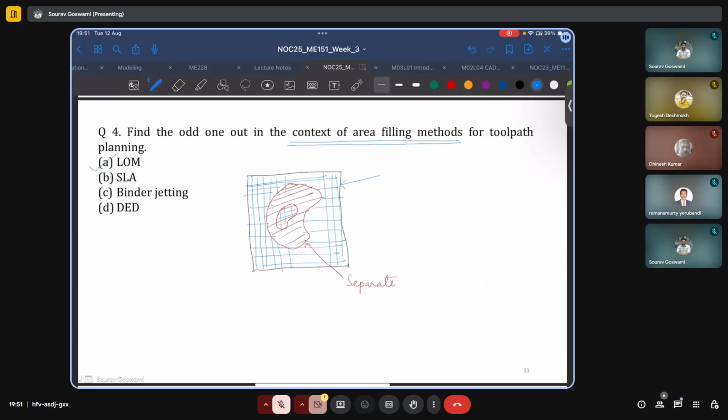But essentially, we have to separate this from the existing sheet. And that is why we are more focused on how to cut it out. First via some very precise cuts with controlled or fine laser spot size, and later using coarser laser spot size or higher speeds without caring so much for accuracy. We just want to cut out the remaining material so that later it is very easy to remove.